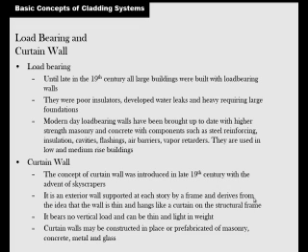So all the buildings were load-bearing. Everything had a structural intent. They weren't very good insulators. They developed water leaks and required larger foundations, obviously, to hold the weight of the walls. Modern-day load-bearing walls have been brought up to date with higher strength masonry and concrete with components such as steel reinforcing. Steel can hold a lot more with less weight. They also include insulation cavities, flashing, air barriers, and vapor retarders.